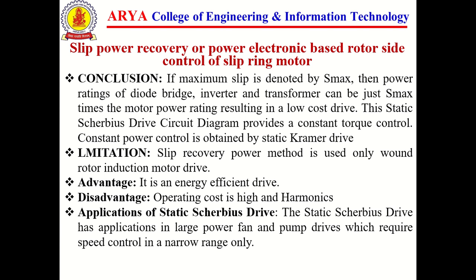And the application of static Scherbius drives, known as the slip power recovery method: the static Scherbius drive has application in large power fan and pump drives, which require speed control in a narrow range. So these are the specific applications of this drive.